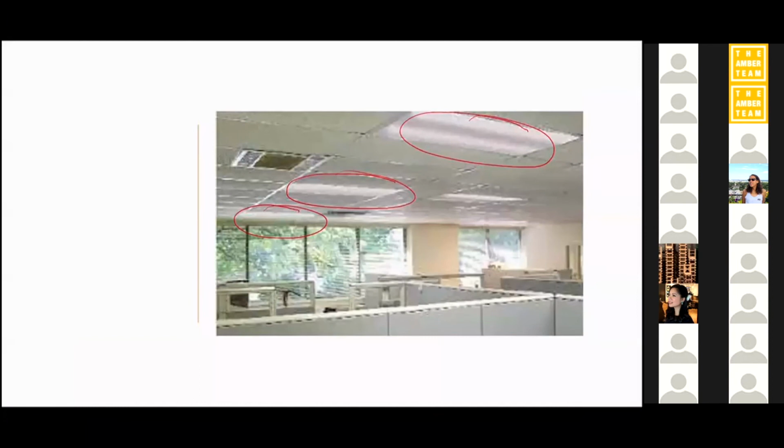And also, importantly, we're limiting the amount of light we're using. And this is a really good idea. If you guys are designing office buildings, daylight harvesting is a great idea, because nobody ever gets up and turns off the light when the sun comes out and then turns it back on. Especially in these open office plans, no one feels the authority, and if they do, they kind of piss off their neighbors. Who are they to go up and turn off the lights? So I'm a huge fan.